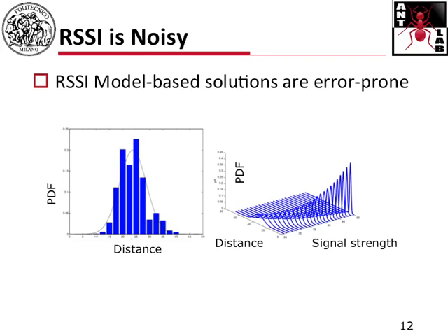As you can see, in real conditions, you have a kind of bell-shaped function, which is around the correct value, say 4 meters. But still, even if you don't move anything in your system, your inversion of the parametric model distance-received power may kick in some errors. So you may have, for example, a non-null probability to estimate a distance which is 2 meters from the real one, or 3 meters from the real one. So why is that?